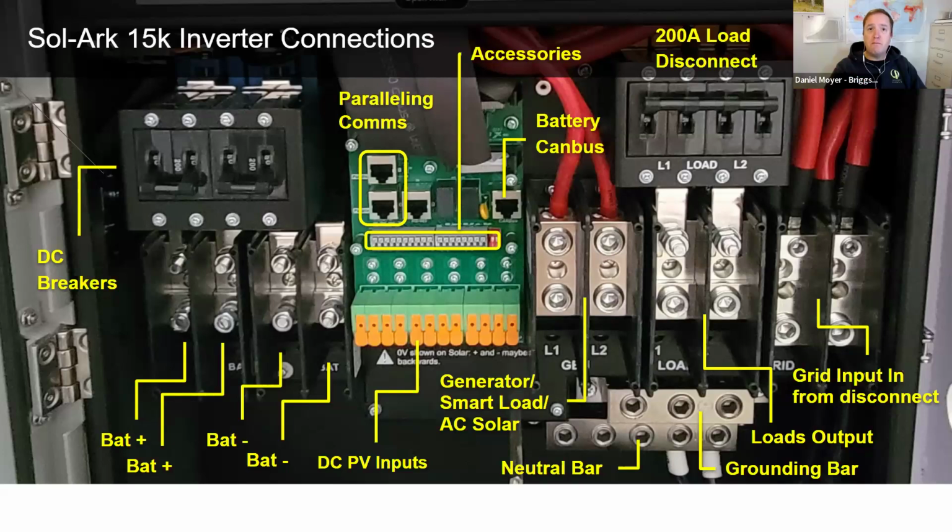Yeah, those are our 3 independent MPPTs, and each of the MPPTs has the ability to parallel up 2 strings. And these are great if you, say, for example, have solar modules on east, south, west facing roofs, that you're not going to be limited by the production of each string as the sun moves across the sky.